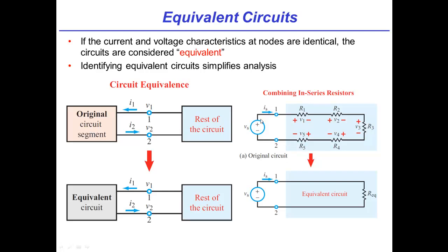And the current is? Right. And it's a loop, so the current has to go through. So the current going into 1 is the same as the current coming out of 2. It's got nowhere else to go. Now we've got some voltage Vs and some current Is. We can replace these 5 resistors by one resistor, provided the value of that resistor ensures that for the voltage Vs, we get the current Is.